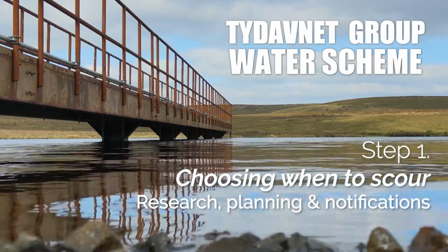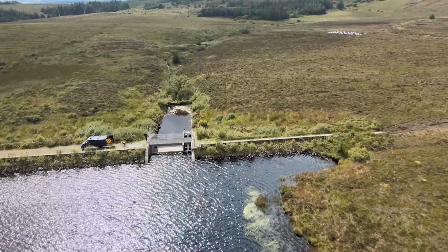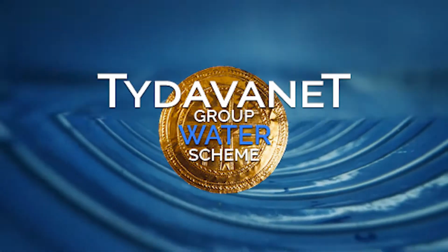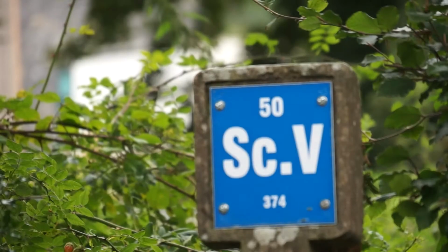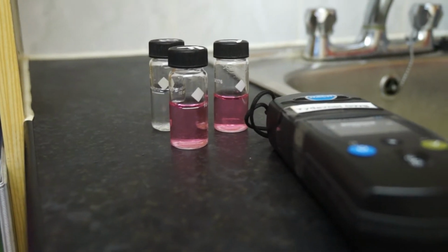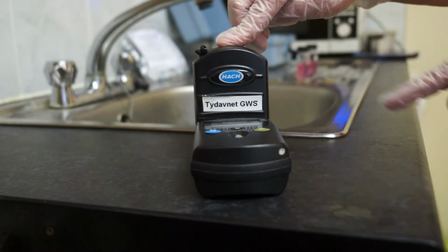To ensure that waters supplied are safe and wholesome when they reach the customer's taps, keeping the distribution network clean is a vital procedure for every group water scheme. The sanitary condition of the distribution network is naturally affected by a buildup of organic or inorganic matter in reservoirs and pipes over time. This makes it harder for the chlorine to do its job, thereby increasing the risk of pathogens in the supply. Beyond this, they contribute to the formation of disinfectant residuals including trihalomethanes.